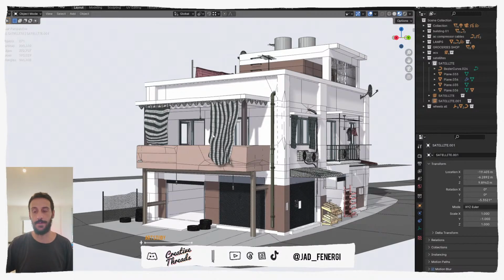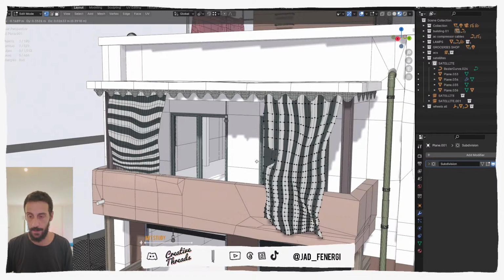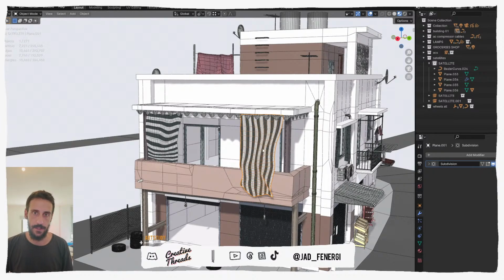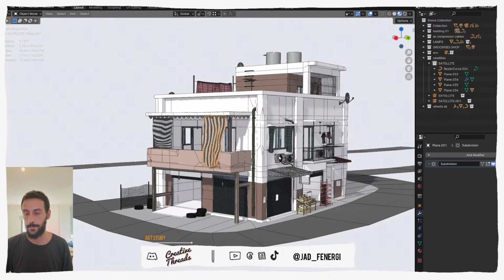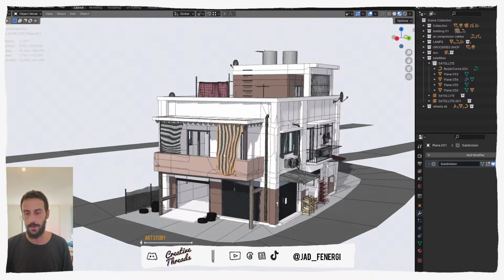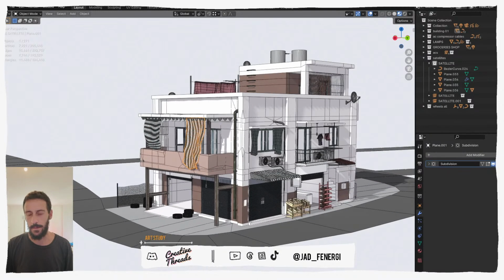I did some things off stream, but I'm mostly happy about fixing the lag that we're facing while moving things in edit mode. After some research, I found on Reddit that if you have some unbaked simulations, because we did some clothing simulations in the early streams, that can affect the performance during edit mode.